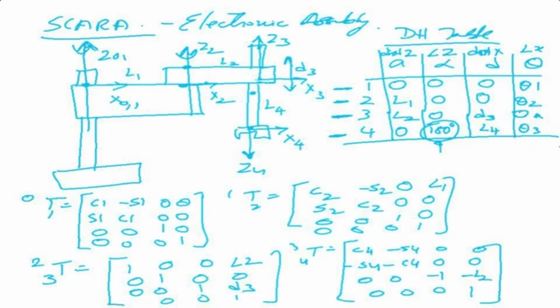So we have got our 4 matrices which are taking you from the 4th frame to the 1st frame. All we need to do is to multiply it out now, and we can get the matrix. This is the reason why we need to understand this DH parameter very, very carefully and very systematically, because the computer program operates like this. All these simulation softwares, for forward kinematics, inverse kinematics, operate like this. So this is what we need to understand.